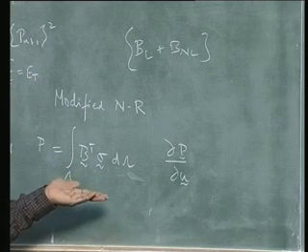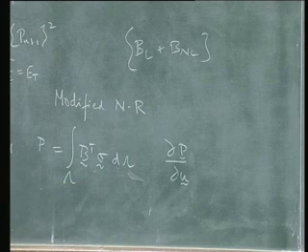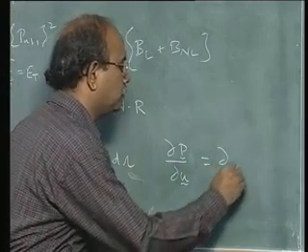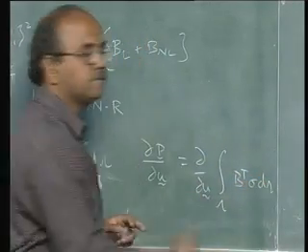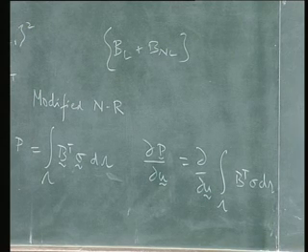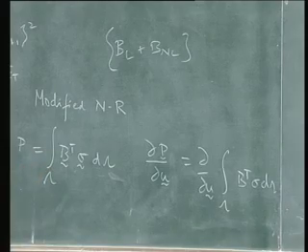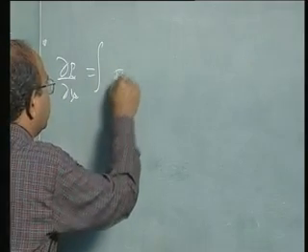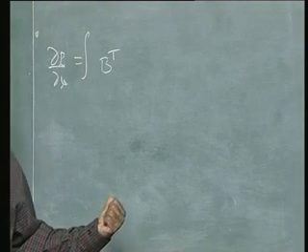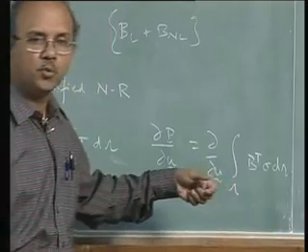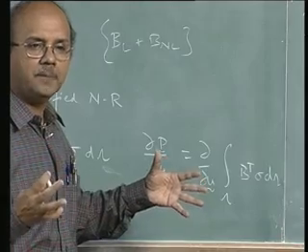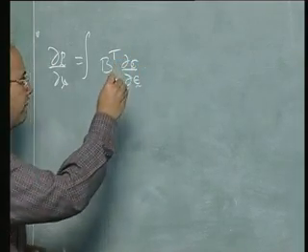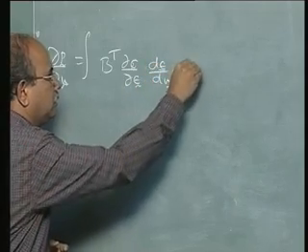So let us now look at, in a very simple fashion, for small deformation, how this can be modified. It's very simple to modify the tangent stiffness. So this would be ∂ by ∂u of the integral of B transpose sigma d omega. So how would I write that? I would write ∂P by ∂u, B being independent, as B transpose. So what would be the next term? ∂sigma by ∂u, but sigma is actually a function of epsilon. Epsilon is a function of u, so you can write this as ∂sigma by ∂epsilon into, I am just using the chain rule, d omega.